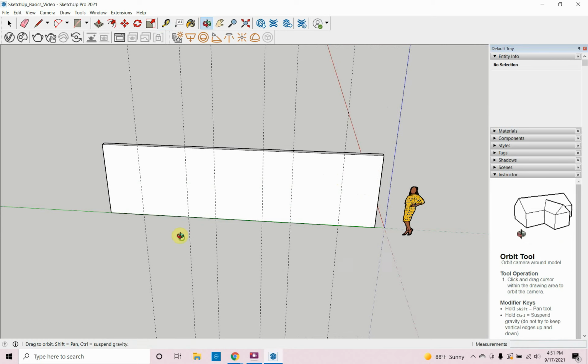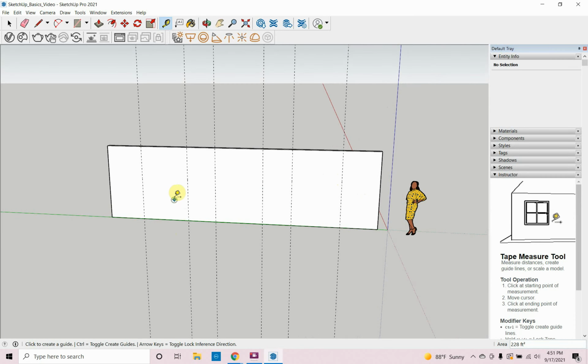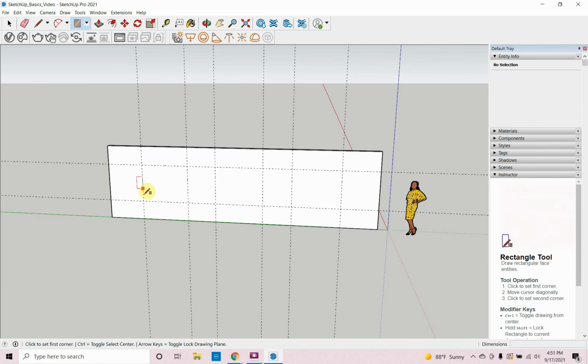Okay. I also want to make sure that these are 2 feet from the top and 2 feet from the bottom. So I'm going to drag down from the top 2 feet and drag up from the bottom 2 feet. Okay, so I'll see in a second where my rectangular windows are going to go. So I'm going to type R for rectangle, and I'm going to draw these in. It'll stay in the rectangle command.